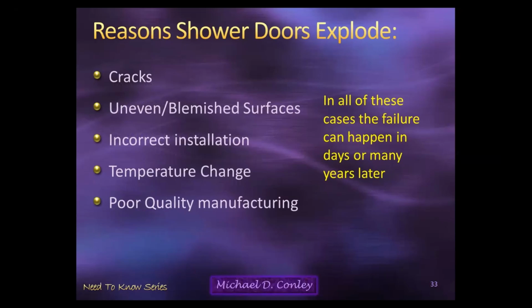Reasons shower or window doors explode: panes explode due to cracks, uneven blemished surfaces, incorrect installation, temperature change, or poor quality manufacturing. In all of these cases, the failure can happen in days or many years later, as the example I showed you with the window pane and the breakfast nook. And this is all part of the manufacturing process to eliminate those things happening, and why when the manufacturer makes the glass, they have to look at it very closely to make sure it doesn't have any of these unseen stresses that could develop later on.